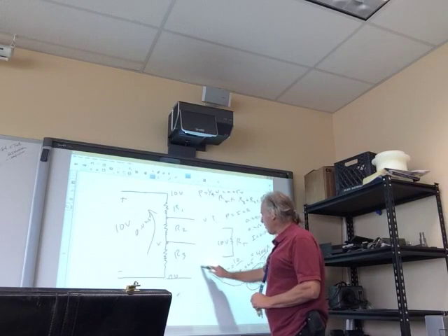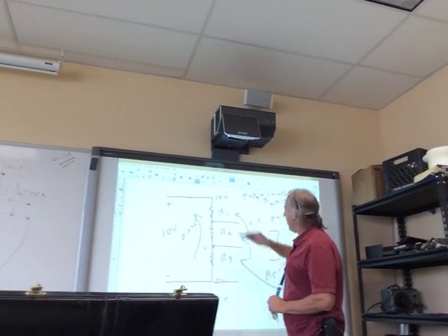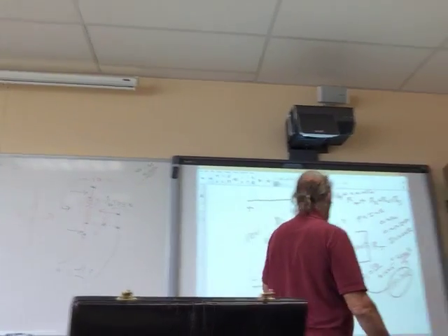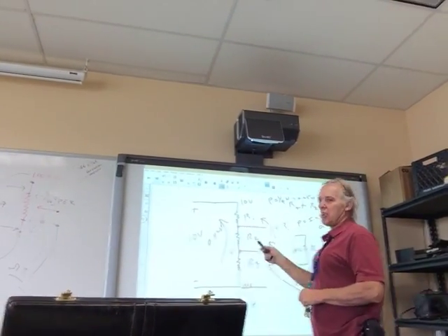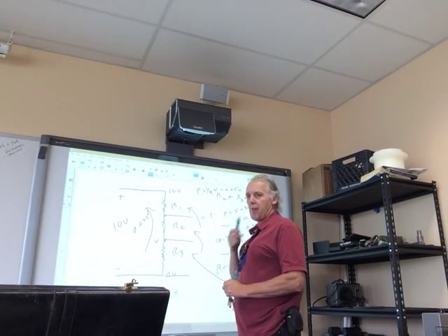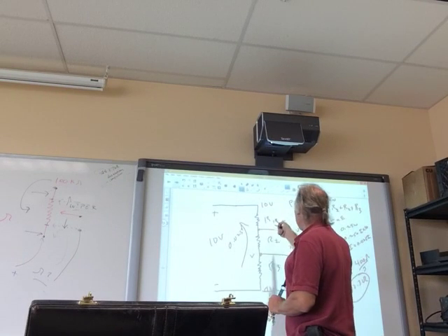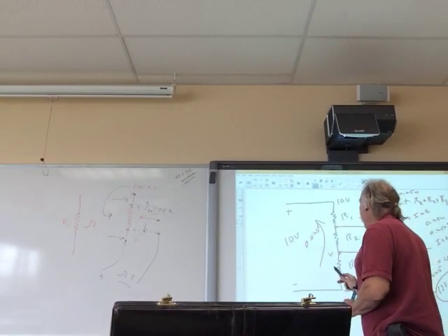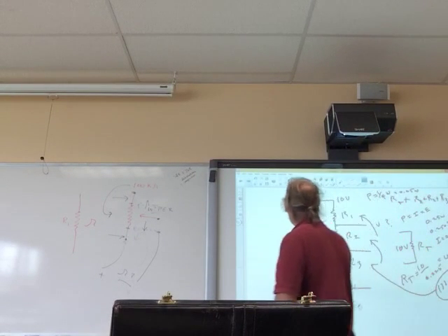So each of these resistors is 133.3 ohms, because I told you they were all the same, didn't I? Yep. Okay, so now we can find the voltage at each of these points, can't we? Because we know the resistance for each resistor and we know the current. So let's see, for R3, let's do it right over here.